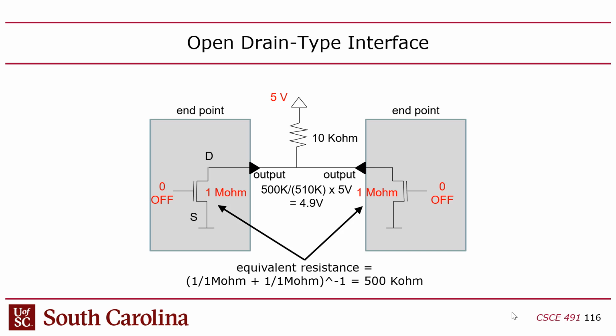And then if one of these guys turns on, so let's say I turn one of these guys on. Oh yeah, and of course the other issue too, by the way, is I will get some leakage current down here. So along with that voltage drop is going to come about 10 microamps of leakage all the time. So this is not as power efficient as a push-pull system.